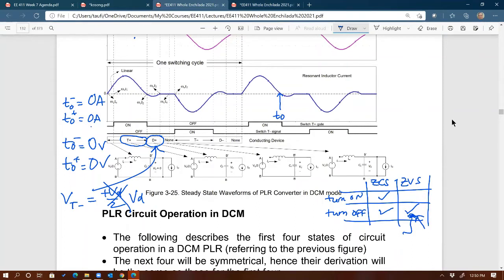If not, the last one. Who wants to volunteer or should I call? Right here, the very last one. I think it's no. For T0 minus, you have no current across the switch or the diode, so they're both off. So the voltage across them would be VD over 2. Okay. Sorry, say it again, Fabian, right?